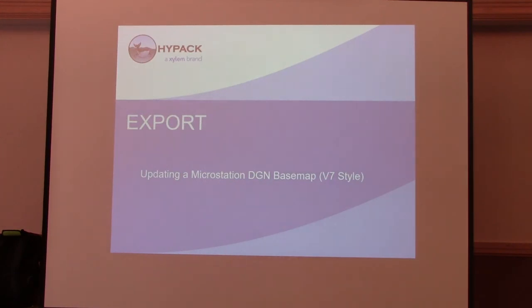Pretty much. I mean, one good thing is that you could draw it as a background file in HYPACK and see how it draws there. So once you generate your DXF or a DGN or something like that, once you close out export, you'll see it'll pop up automatically in the background files folder in HYPACK. Or you can just go refresh. If you want to keep the export program up, just enable it on the screen and see how it looks there, because we'll be able to draw all the stuff that we're able to export, as far as the DXF and DGN files and everything. That's usually the best way.